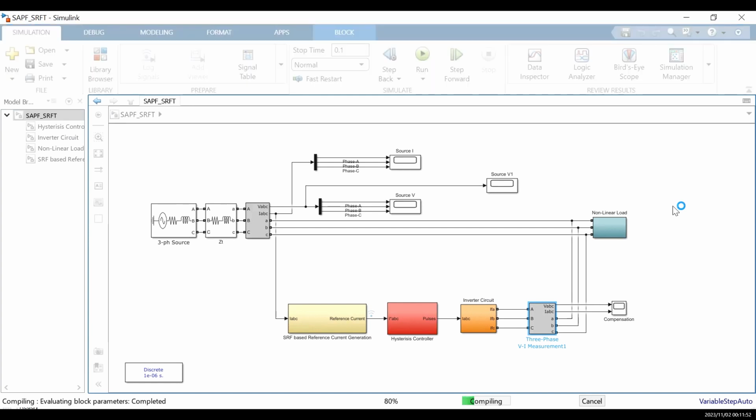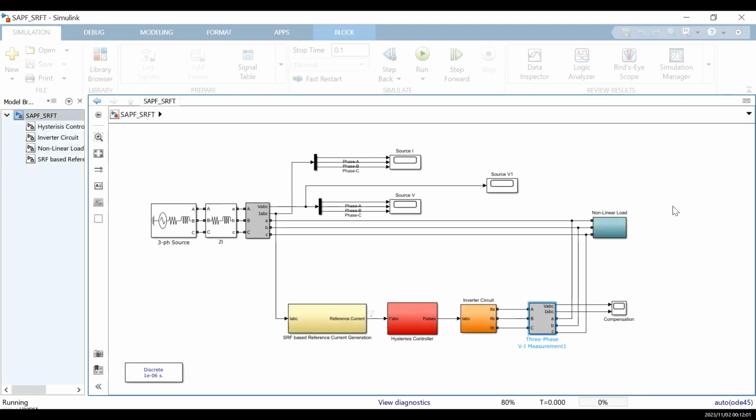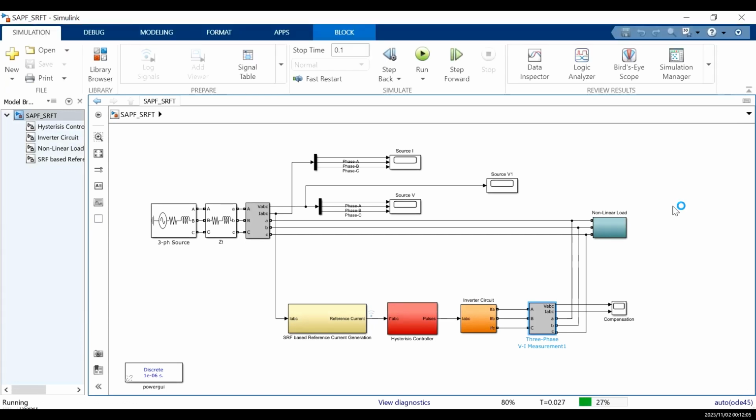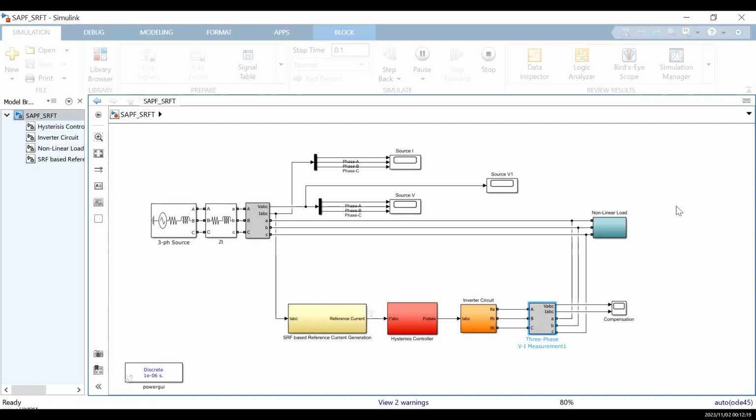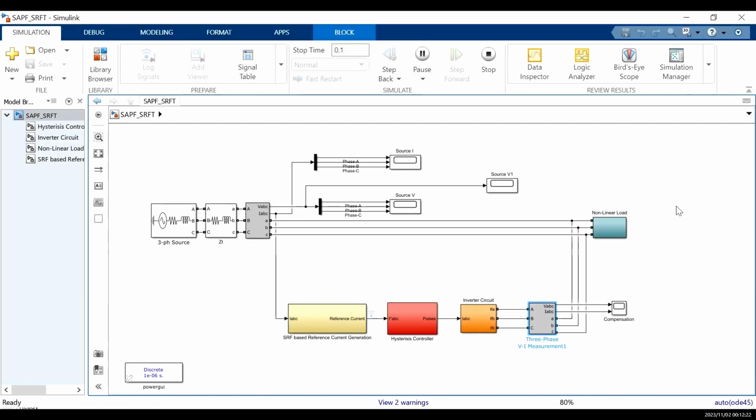Advantages and applications. 1. Efficiency and precision. Three-phase VSIs offer high efficiency due to their ability to control the output waveform precisely. This precision is crucial in applications where accurate control of motor speed, torque, and direction is necessary. 2. Regenerative braking. In motor drive applications, three-phase VSIs can operate in regenerative mode, allowing them to convert excess energy back into the DC supply, improving overall energy efficiency and reducing heat dissipation.